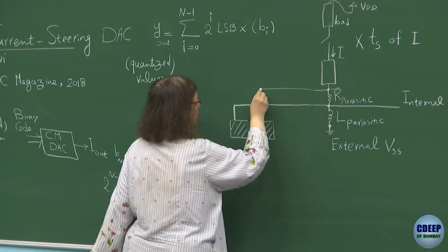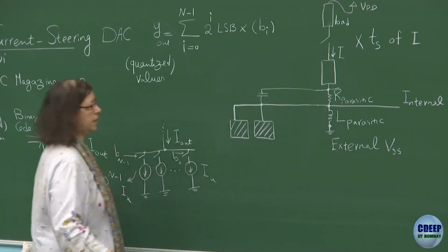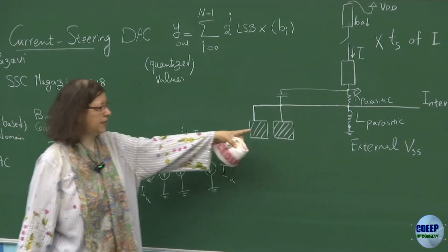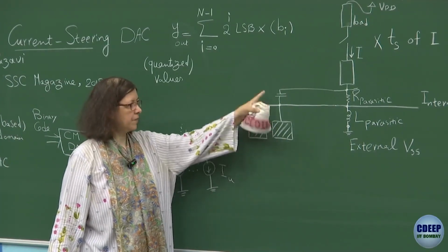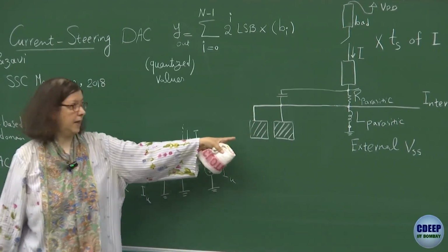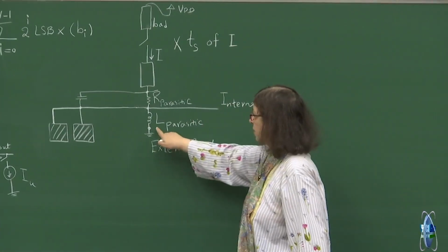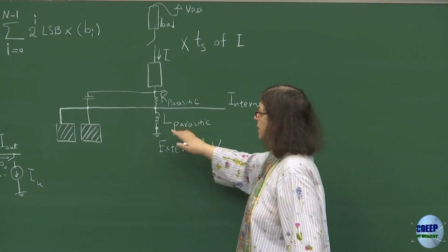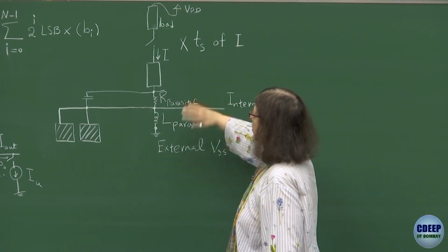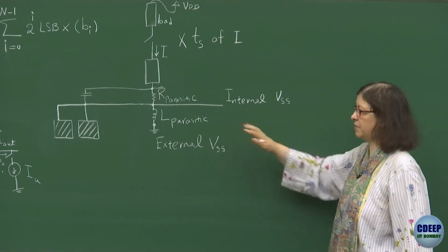Then we also try to add capacitors here, because there is a resistor here, a large capacitor, so that all these nodes effectively absorb any very high bouncing on the line. And this bouncing is created because of this inductor. That's one of the reasons we really don't want a high current going on and off continuously, because of the parasitic effects.